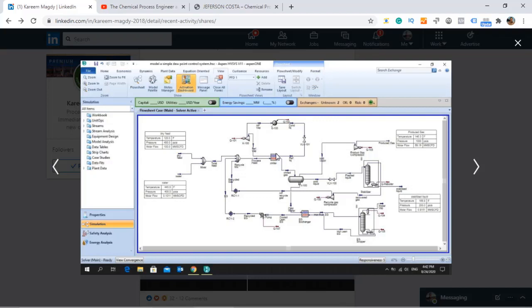You can see that the source of refrigeration for decreasing the gas temperature is a closed loop. So we have here probably a propane closed loop, where we have compression of the gas, cooling of the gas, and because of that we liquefy the stream, and with the expansion we reduce the temperature of this stream in order to have a cold stream, with enough energy to exchange with the hot stream, and this is it.